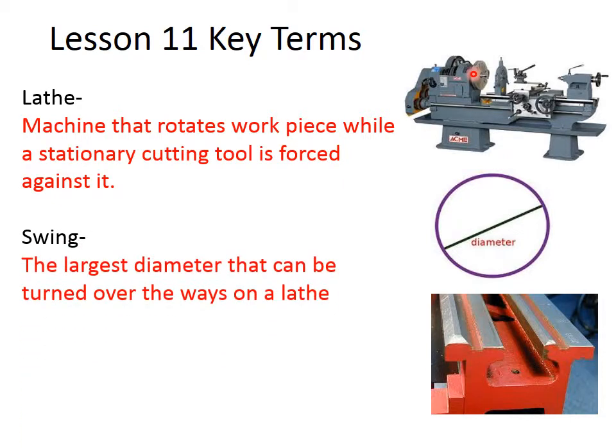Lathes are measured by something called the swing. So the largest diameter, I've got this graphic here, the largest diameter that can be turned over the ways on a lathe is the swing. So that's also how they're sized.